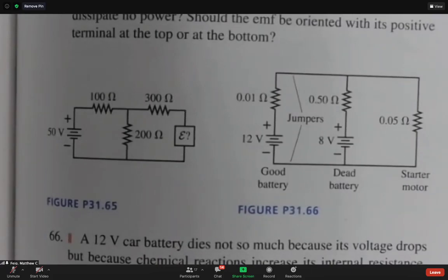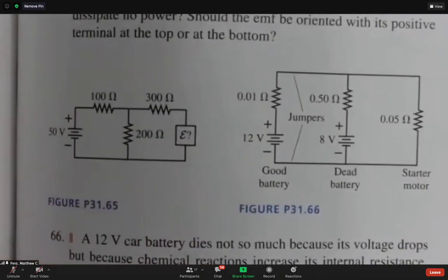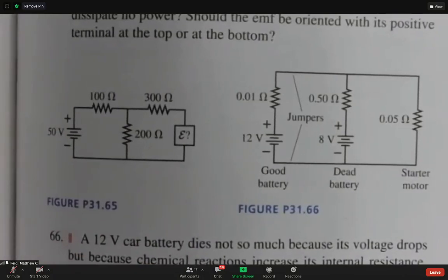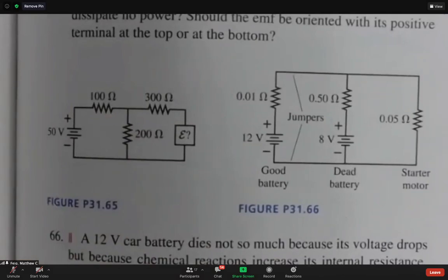If you wanted to, you could just write out Kirchhoff's rules, and at some point you're going to plug in I2 equals 0. You could do that in a more intuitive way and say, this is what will happen if there's no current here. Or you could just say, these 3 equations describe the circuit at all operating values, and I just want to now say, I don't know this voltage, instead I know a current. It's a little bit of a one-for-one game.